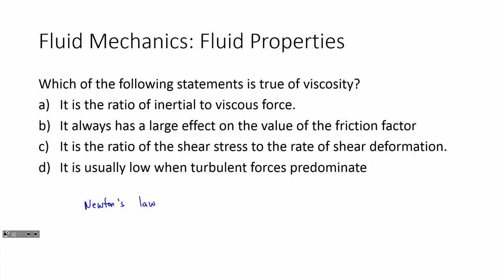So we can use Newton's law of viscosity here to say that the shear stress is going to equal viscosity times du/dy. Okay? So this is going to be shear stress, and this is going to be the rate of shear deformation.